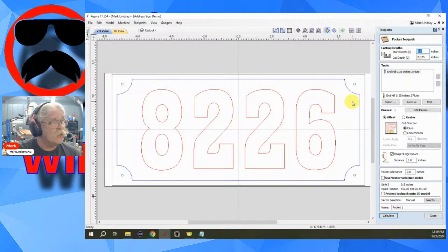Now I'm going to go ahead and just cut to, let's cut, I don't know. I'm torn between 1/8 and 1/4. I'll try 1/4 of an inch, and we'll see what that looks like. 1/4 of an inch, about 6 millimeters. So we'll change that to 0.25. That's how deep I want this to cut.